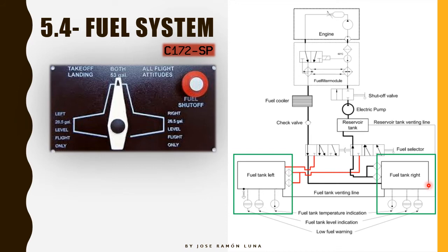So why temperature? Well, if you get the manual or any manual of a plane that burns jet fuel, the temperature of the engine, and not the engine, the temperature of the fuel always comes into play. When jet fuel cools down too much, it forms something called paraffin, okay, and it can block the fuel line. So it's really important to keep jet fuel at the correct temperatures. Each manufacturer, each builder is going to give you the guidelines.